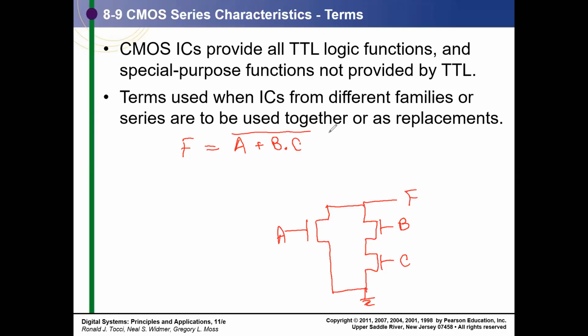Now this is my VDD, and from VDD to F, I need to make a P network which is the dual of this. To find a dual, if it is just 1, 2, 3 transistors, I can directly make the dual. But there should be a method. How do you draw a dual network if it is a complex network? You can use graph theory.